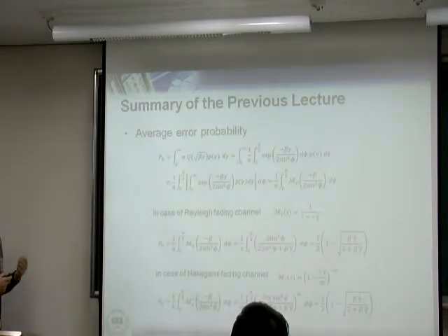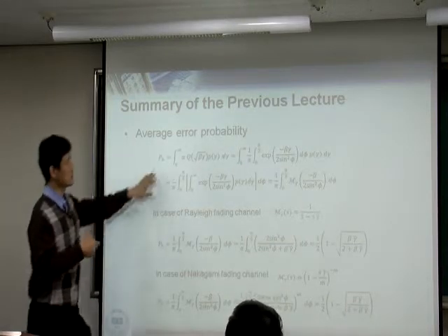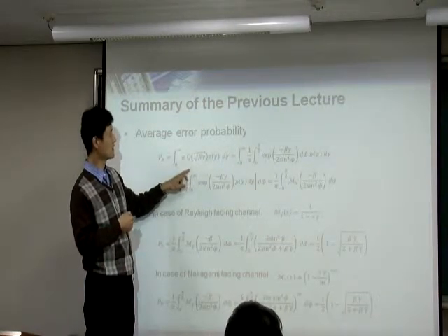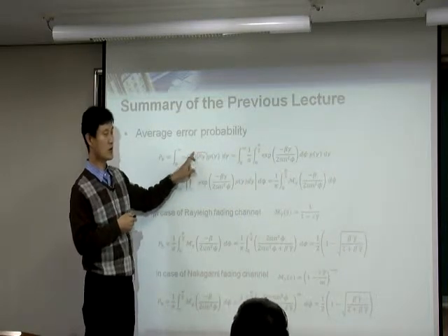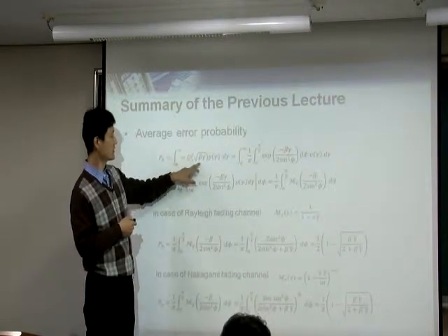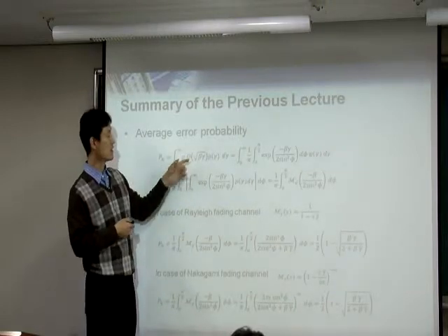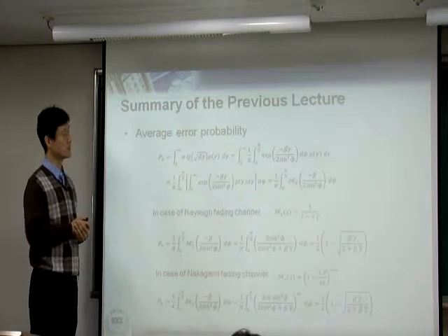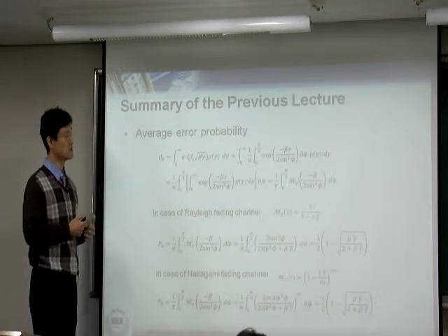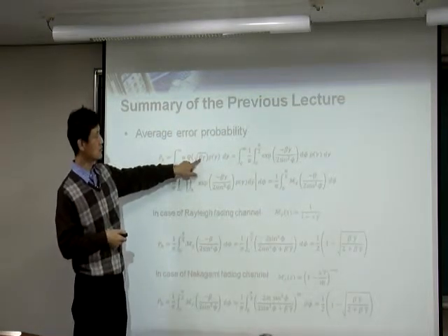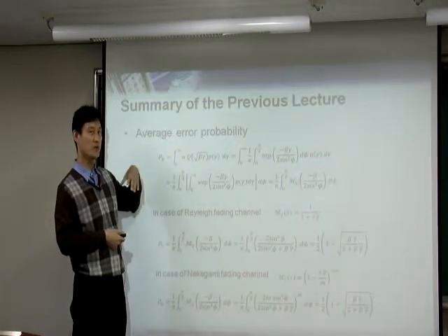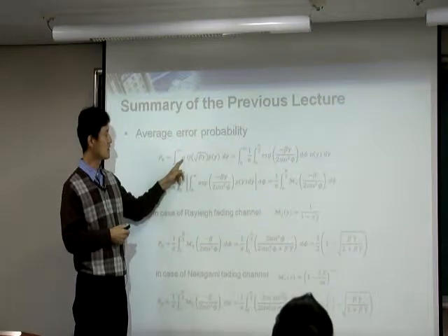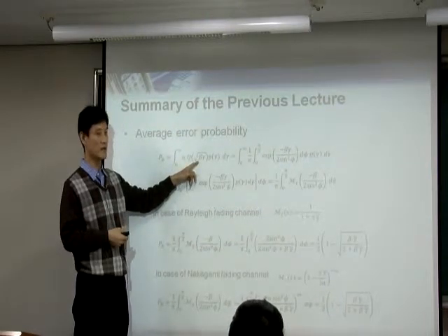So using those things, as I mentioned earlier, in this example, by the way, this example is to find the bit error rate for any modulation. You see that there's alpha here, there's a beta here. These alpha, beta are constants that depend on your modulation. If you use BPSK, generally this is 2, this is 1. If you use another modulation, higher order modulation, you can find its own alpha and beta.